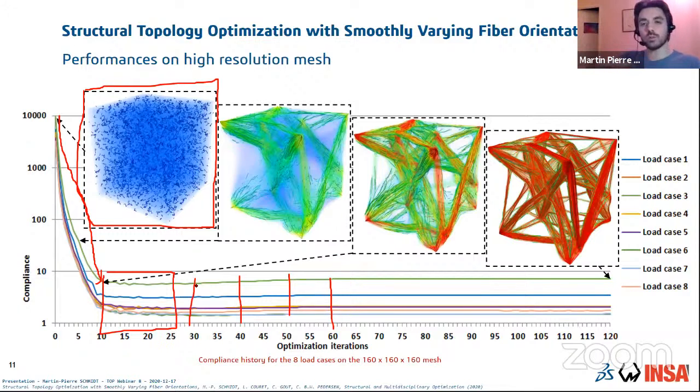If we want to do optimization in a 2D plate with fiber orientations, then this is potentially manufacturable, and this can be done by just adding one design variable field. And if we want to do full 3D, then it probably isn't quite manufacturable, at least not with continuous fiber with today's technology.